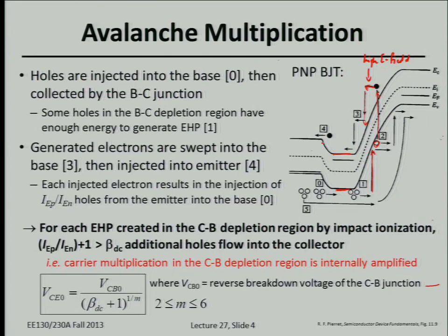So realistically, what's going on? If an electron is generated in the base-collector junction depletion region, because of the electric field it will go to the base, and then the base will be negatively charged. The base gets charged up by electrons, and that eventually reduces the forward bias on the base-emitter junction. So the generated electron has to diffuse into the emitter. Otherwise it will just stay in the base and forward bias the base more, which lowers the potential barrier and causes electrons to flow across.